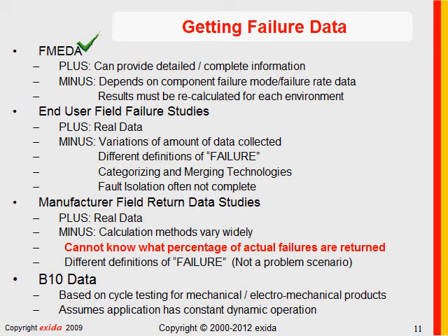The advantage of this is that it's very detailed and very complete, but of course one FMEDA may not be the same as the other because the FMEDAs depend on a good component failure rate database. One can get failure rate data from end-user field failure studies. The problem with these is that in the many failure rate studies that I have done at Exida, I've found tremendous variations in the amount of data collected.